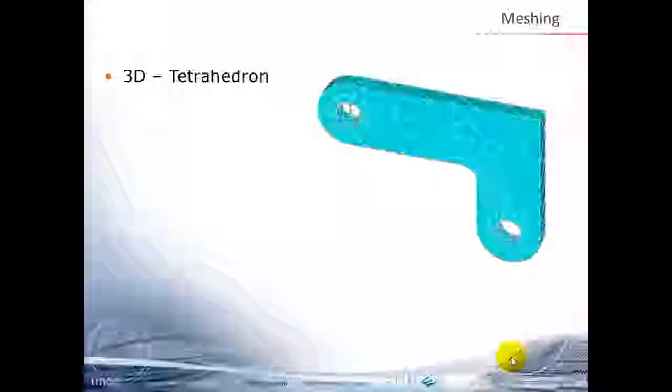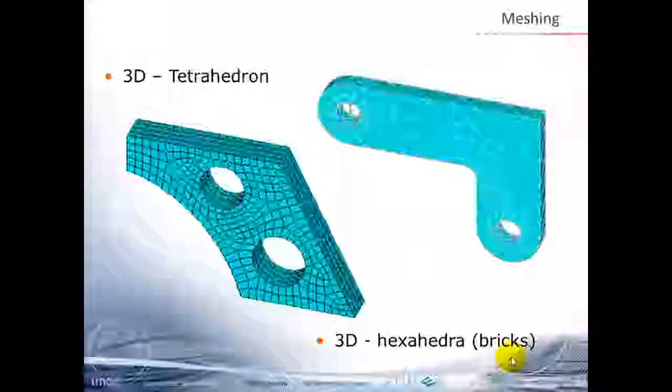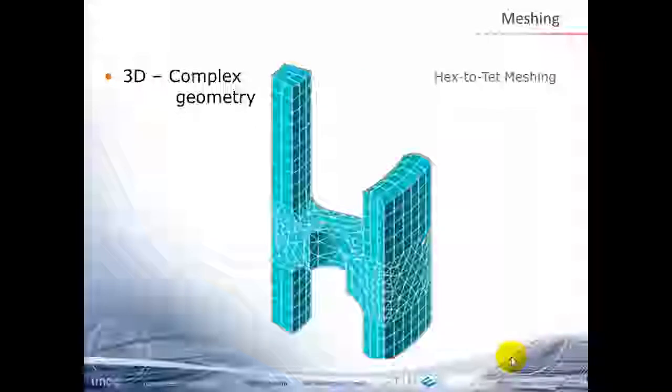In the 3D world you have the equivalent, but then it's called the tetrahedron, or the four-faced element. You can sometimes use brick elements. In this case, one face was meshed with the quad elements, and it was extruded in the Z direction. And for complex geometries, you can have a mixture of elements.